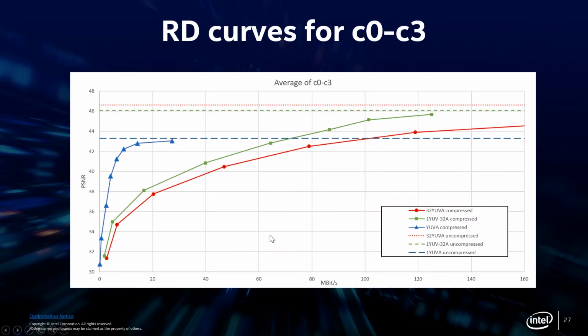We've also drawn some horizontal dotted lines. The lowest dotted line shows the PSNR value we're able to achieve before we applied video compression. This is the PSNR value you can achieve prior to compression, and it serves as a theoretical maximum quality level for that format of content.